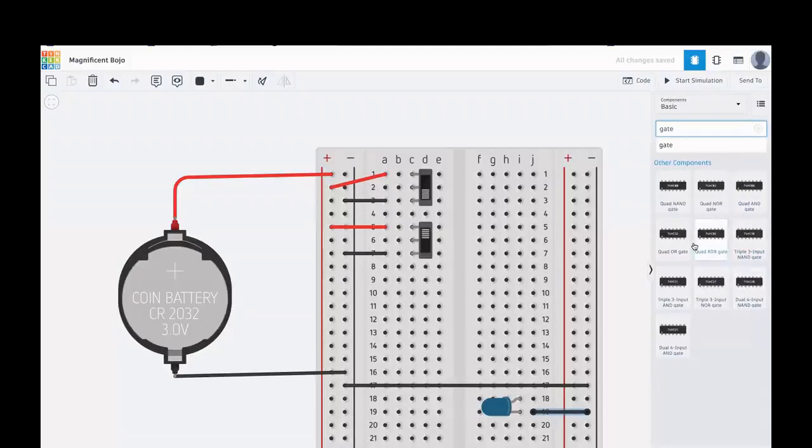It's important to acknowledge that the gates that we have are ANDs, ORs, XORs, NANDs, and NORs. You see that we do not have any NOT gates. So to make a NOT gate, you're going to have to use either the NANDs or the NORs. The ones that don't say inputs are just 2 inputs, so NAND, NOR, and OR. These top ones have 4 gates of 2 inputs. You see we have a 3 input AND, NAND, NOR, and on some of them we have 4 inputs.